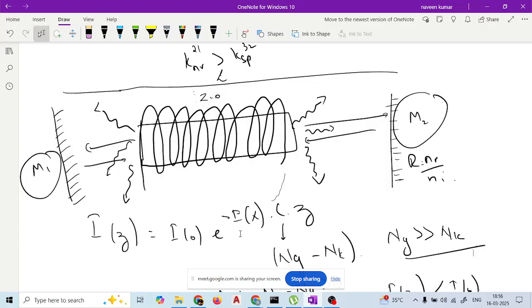So let us do a little analysis of what is exactly happening in the system. The gain media is the media in which we hope to convert light energy of one kind, incoherent light, into coherent light. The light energy existing as incoherent light from the discharge lamp or flash lamp is used to generate the fluorescence. Now we want to make sure that the energy delivered through the flash lamp is efficiently converted into the energy of photons of stimulated emission or not.